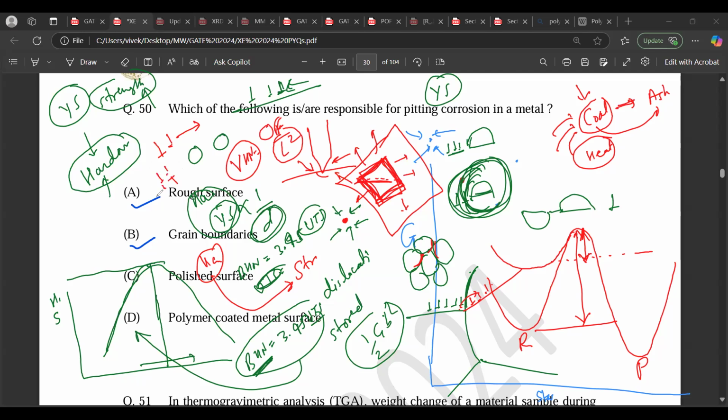And they will entangle and stop moving, and that is where the material shows the resistance, because the dislocation is no longer able to move at a particular force. That is how the resistance is calculated. So actually it's resistance to the movement of dislocation. And in strength also it's the same, resistance to the movement of dislocation. That is why hardness and strength are correlated.